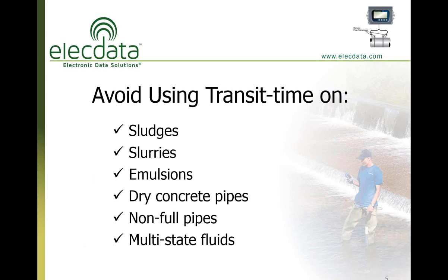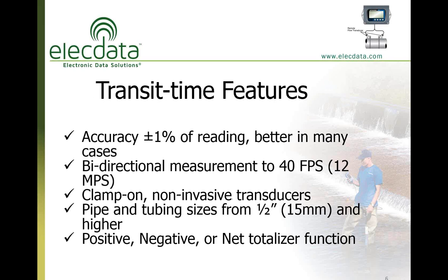You'll want to avoid using transit time technology on any of the following: sludges, slurries, emulsions, dry concrete pipes, non-full pipes, and multi-state fluids.